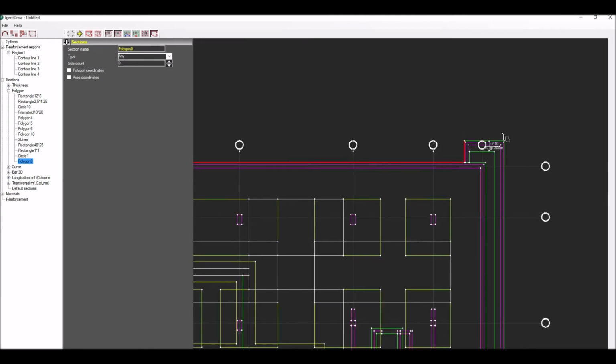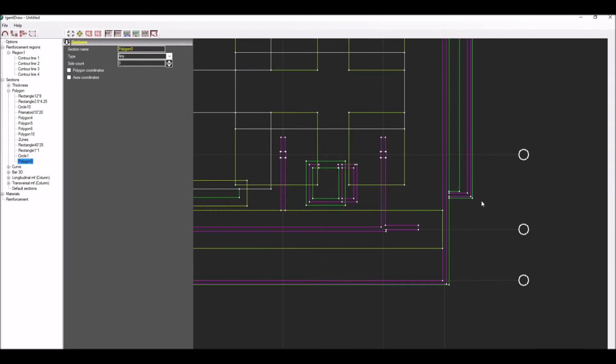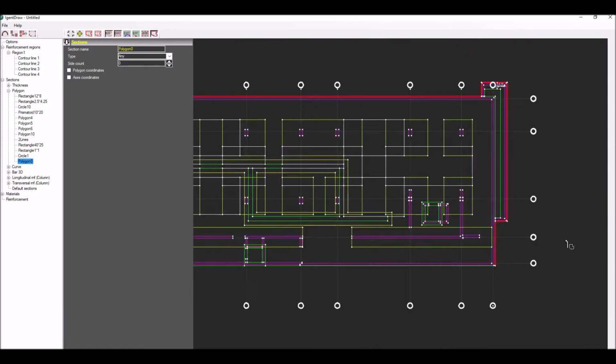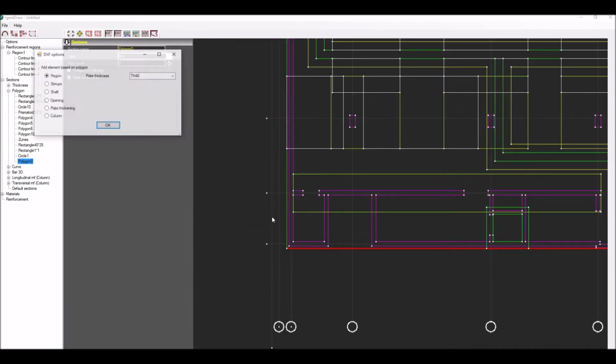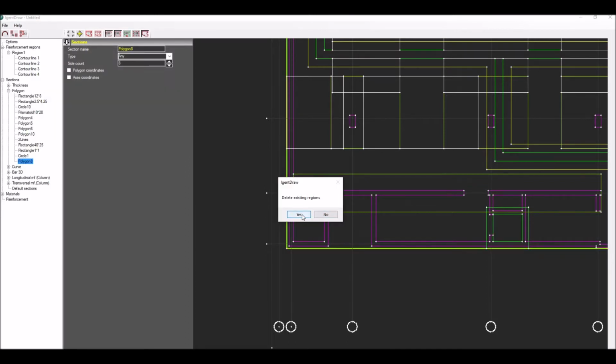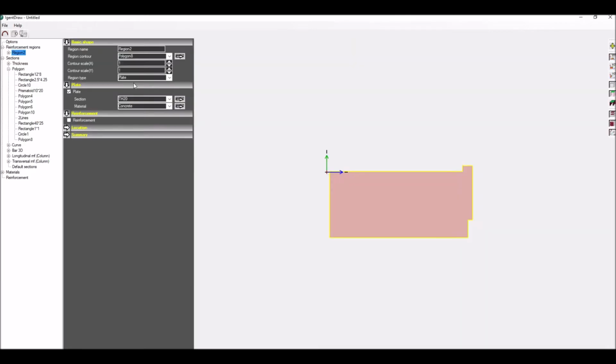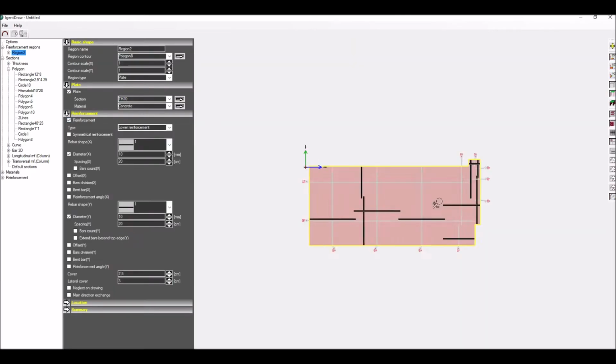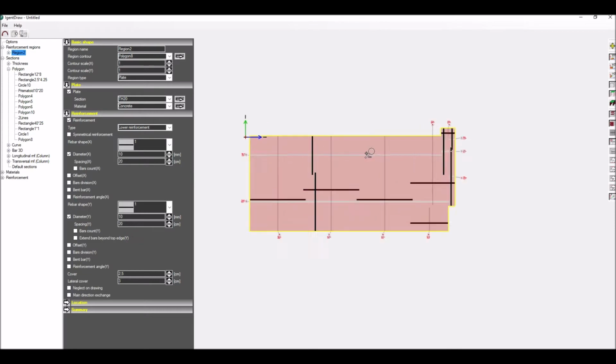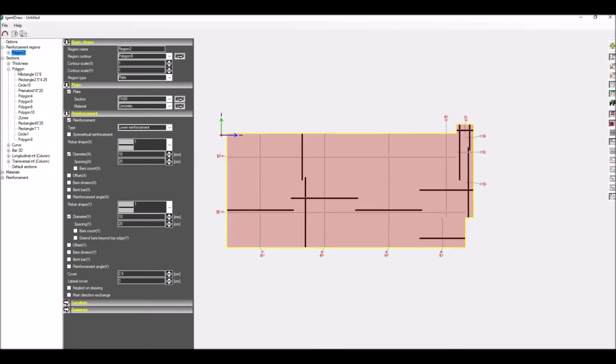There are a few ways of contour generation. Here I define it by clicking subsequent points with automatic snapping to background points. When contour is defined, it is sufficient to switch on reinforcement checkbox to automatically get drawing with default parameters. These parameters can be later changed freely.